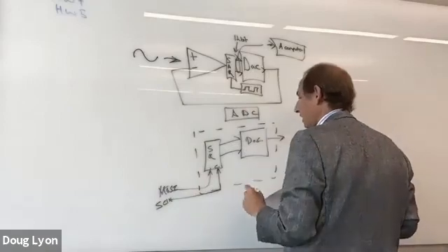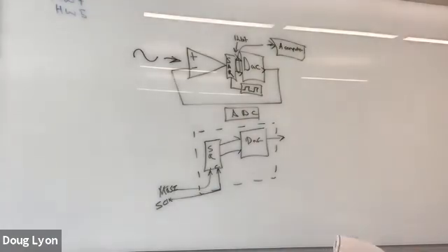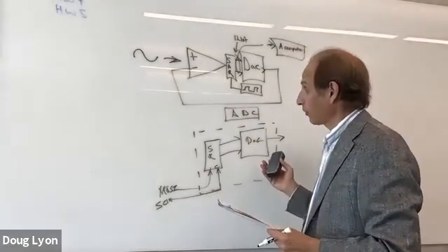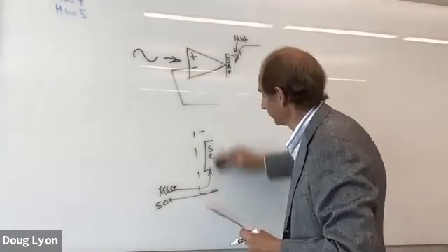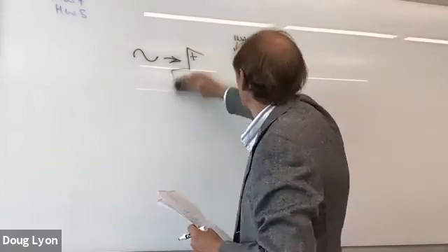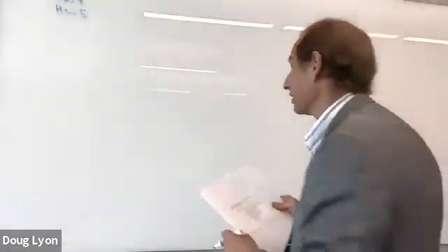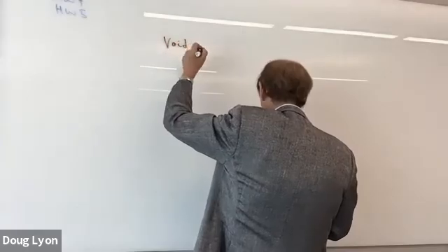All of this is contained inside of the MCP 4921 DAC. And so what we need to do as programmers is write out 16-bit quantities to the DAC, and we're going to do it one byte at a time. And this is how you write a device driver for a little chip like this. I mean, you've got to do it. It may be done for you, but eventually you're going to end up doing it yourself.